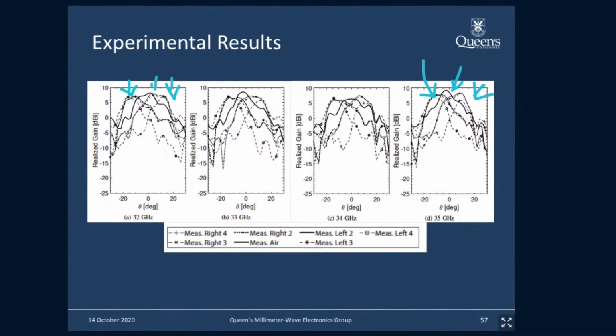Here we actually have beam steering with a single element, in one direction. So in fact, what this means is that if we wanted to do beam steering in 2 dimensions, we could just put a few of these antennas in series, and then we could potentially do 2D beam steering.